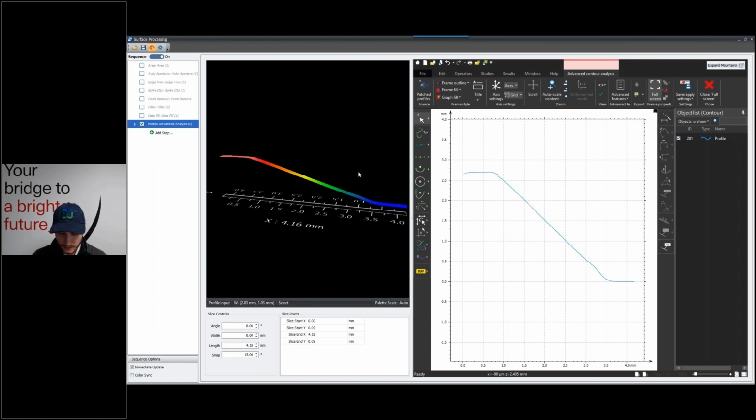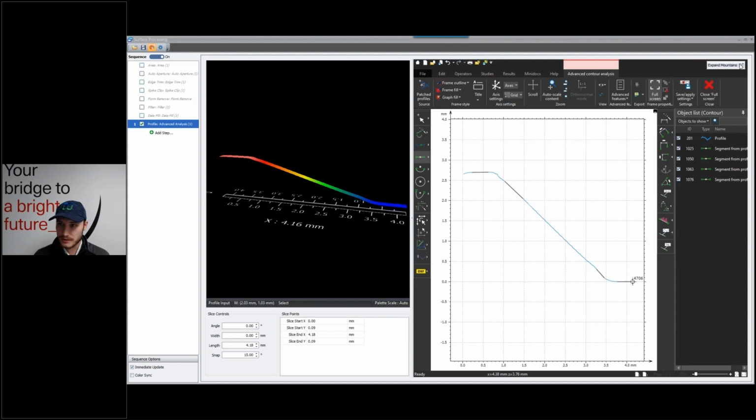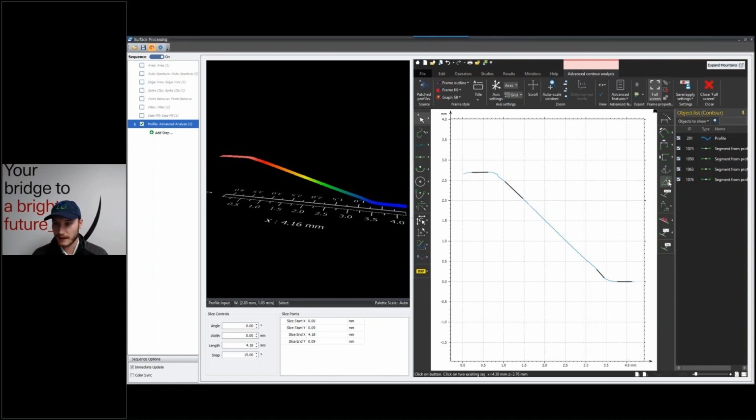So I'm going to make a very quick angle measurement. We are going to create two segments, one at the top here and one over here. And then for our reference, I'm going to create one right here and one over here. And scooch this out of the way. And so very quickly, angle over here. We're actually interested in the supplementary angle, but I'll get the two angles set up for you real quick.